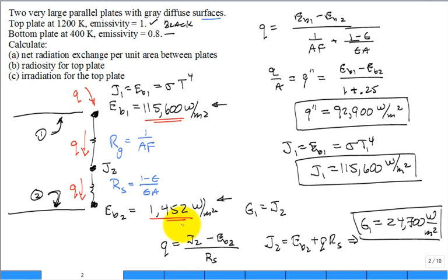But is there such a huge difference between the temperatures of 1200 and 400? Not really. I mean, it's only a factor of 3 to go from there to there, true? Is there a factor of 3 if I just take 1500 multiplied by 3? Do I get... No, not at all. That's the power of the T to the fourth. You almost have to see it in action to say, that number, did I run this correctly? Are these two numbers that much different? It's the temperature to the fourth power in that Stefan-Boltzmann law that makes the high temperature so much greater black body emissive flux.